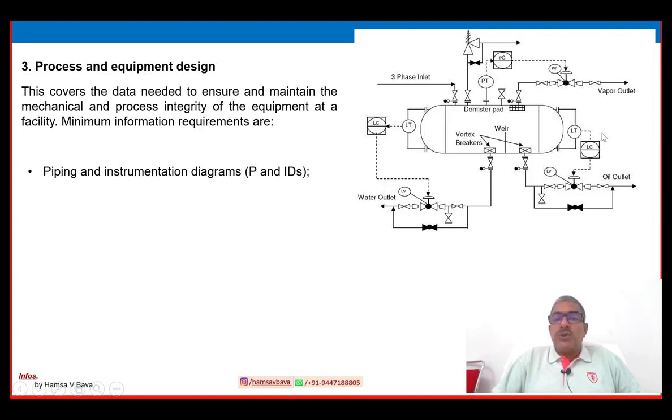Some alarms will also be provided here, like level switch low low, level switch high high, pressure switch low low, pressure switch high high. Some internals of the separator are shown, and pipeline dimensions and pipeline details are shown, along with various instrument signals and electronic signals. So more and more details are provided.